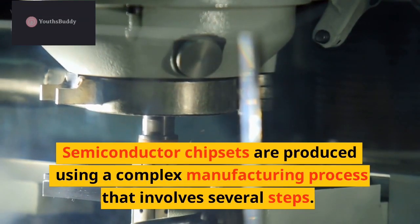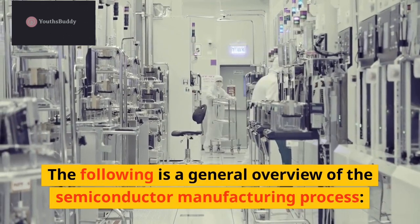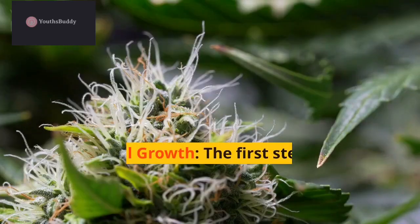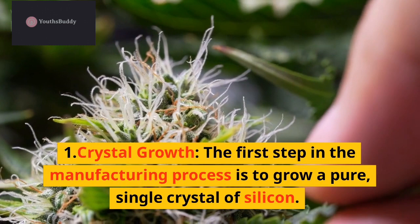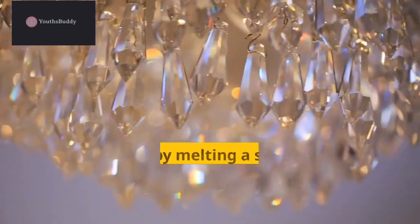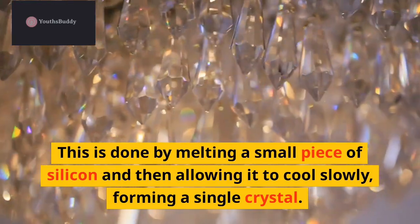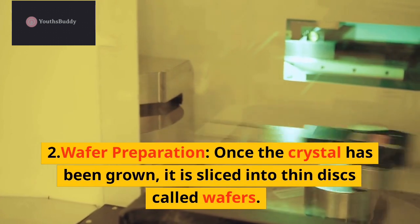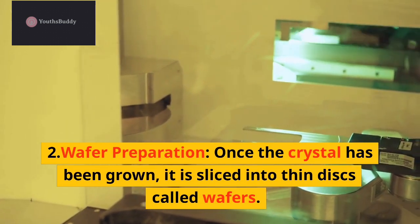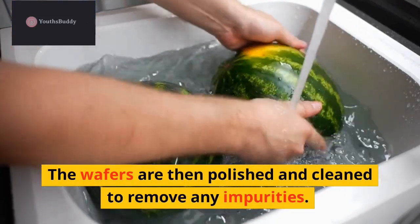Semiconductor chipsets are produced using a complex manufacturing process that involves several steps. The following is a general overview of the semiconductor manufacturing process. 1. Crystal growth. The first step in the manufacturing process is to grow a pure, single crystal of silicon. This is done by melting a small piece of silicon and then allowing it to cool slowly, forming a single crystal. 2. Wafer preparation. Once the crystal has been grown, it is sliced into thin discs called wafers. The wafers are then polished and cleaned to remove any impurities.